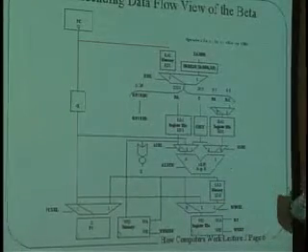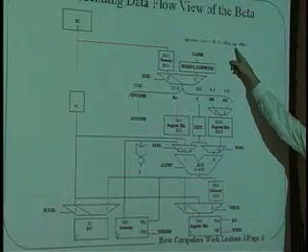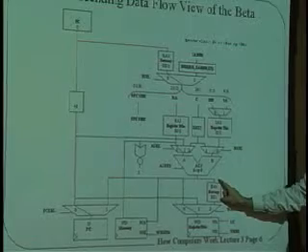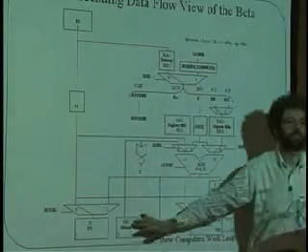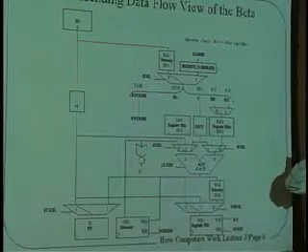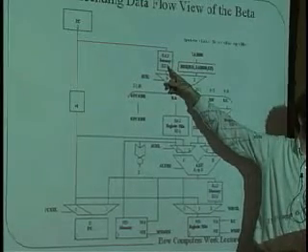But the other thing to note is that even though this is an operate class of instruction like an add, notice that this is not being used, even though it's in the data path here, and notice that this isn't being used either. This is the write to the memory, this is the read from the memory. The only part of the memory read that's being used is this one here, which is where we're fetching what the instruction is that we need to do.